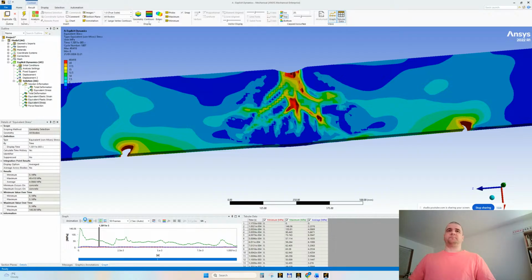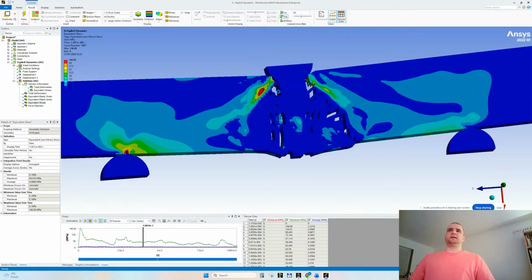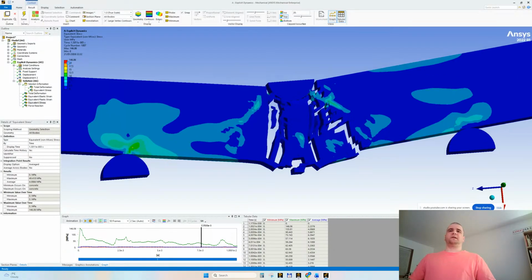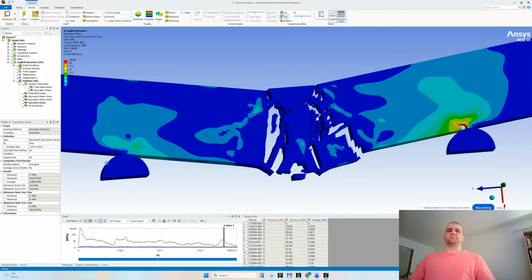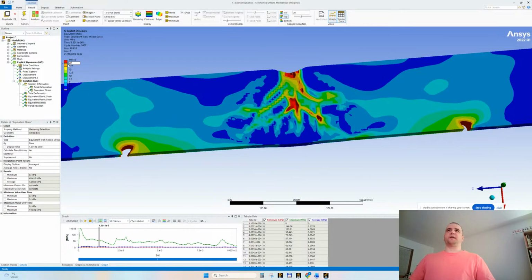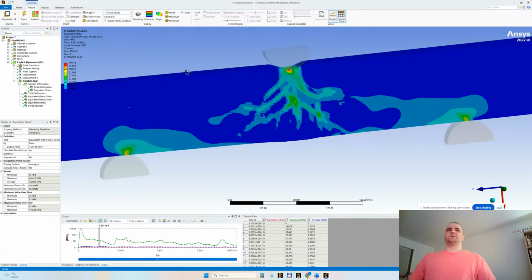So it's not very realistic. So it broke, then it gets back. Because it's related only to the value. It's not about the realism of the mesh erosion. Yes? This is a workaround in static and transient, not here in explicit, all right? Here in explicit, let's go back to exterior, we do have mesh erosion.